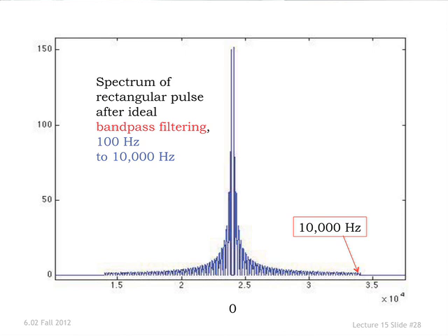So what comes out is something that has this spectral characteristic. And you can see that the frequency content is sharply limited 10 kilohertz above 0. And then there's actually a central region that's entirely missing. So remember, this had to go originally up to 256, but because we've chopped out the center portion, we're only going up to 150-something out there.